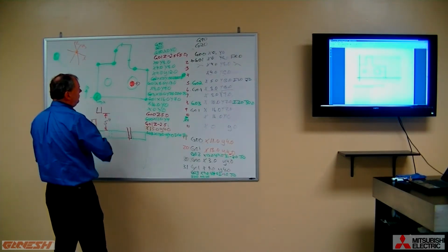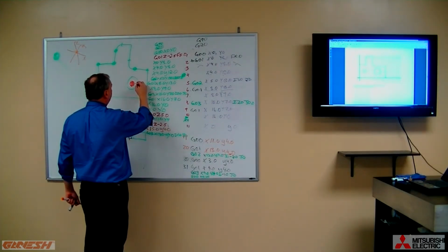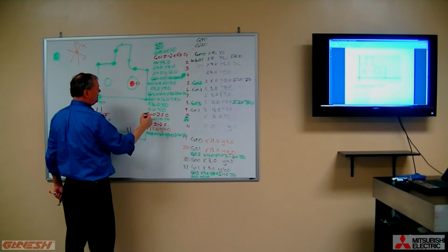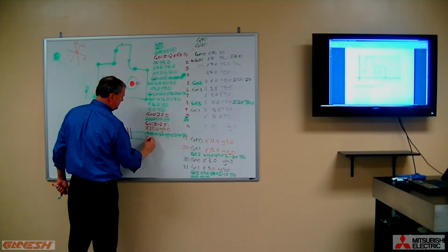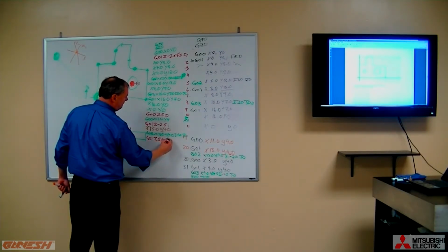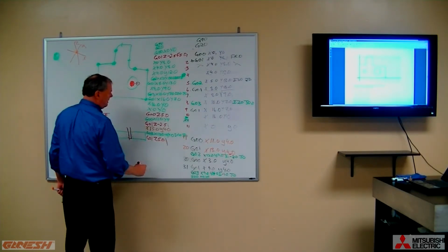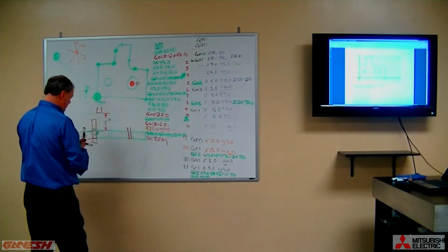And if you want to, you can pull the Z up right from this position. Some people would prefer to bring it back to the center, in which case we would just say G01, but we'll just lift the Z up slowly. We'll say G01, Z5.0. And now we're sitting up in the air, and we want to wrap it over to the other hole.